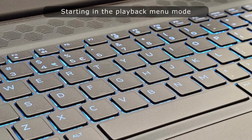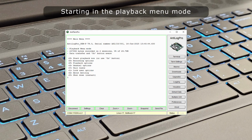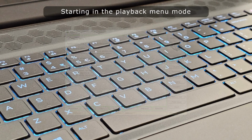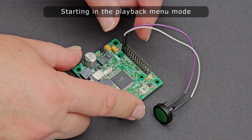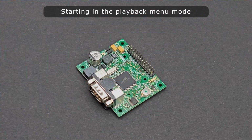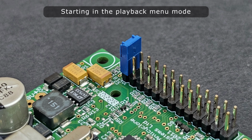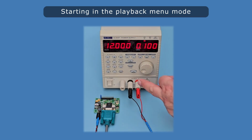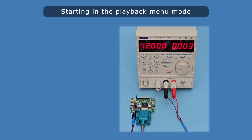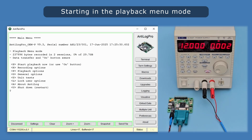There is a simple way to start your unit up in the playback menu mode, so you see the menu system without having to wire anything up. Normally, you would press and hold a push to make button wired into the J3 header during power up. However, you can simulate this for a quick start by fitting a jumper link across pins 1 and 2 of the J3 header and then applying power. After 2 seconds, remove the link and you will see the main menu appear on your terminal display.